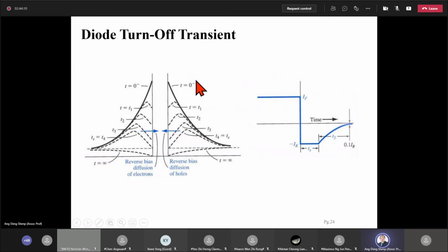So at the very time you toggle the switch, pretty much the same excess minority carrier charge is stored on both sides of the junction. In other words, even if you toggle the switch from left to right, you can think of the diode as remaining forward bias, but the direction of the current can change. And the current flowing through the diode can also be quite large, because the current can be supported by the extraction of the excess minority carrier charge stored.